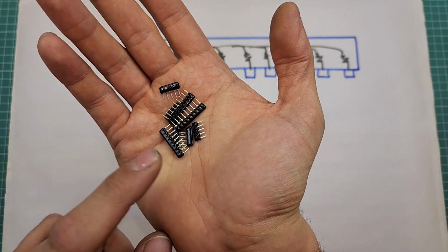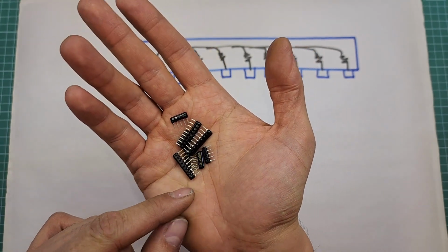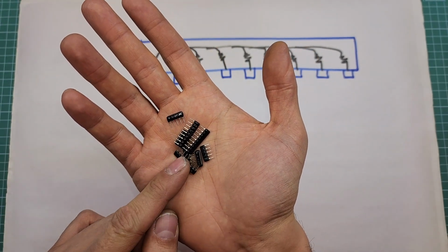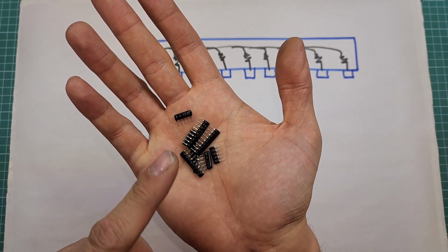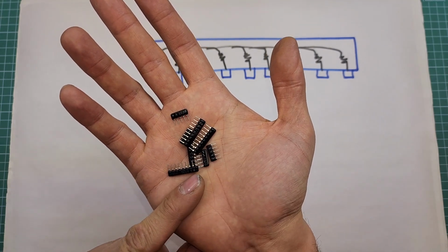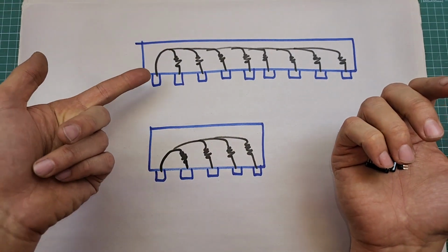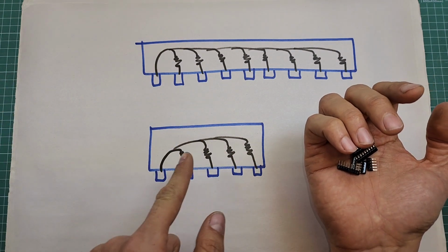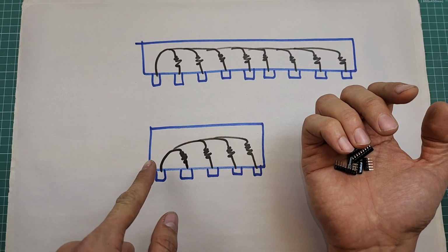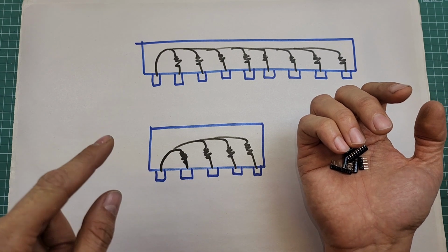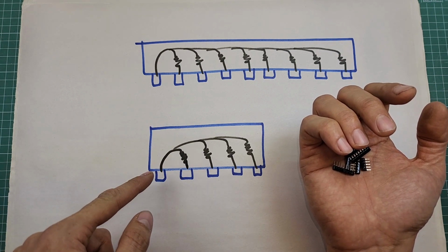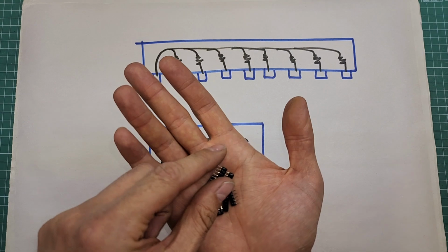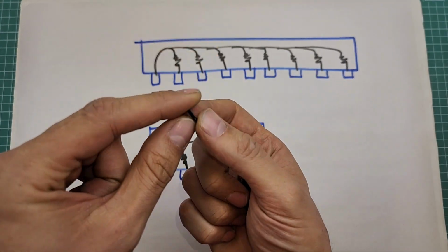They usually have one common pin and several pins from each of the internal resistors. The number of pins on these resistor arrays is usually an odd number, like 5 or 9 pins. A 5-pin resistor array consists of 4 internal resistors with 1 pin from each connected together and brought out to the common pin like this. There is usually a dot on the common pin to identify it, see?